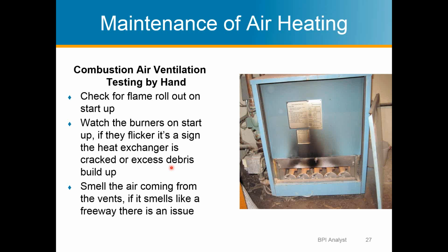When the large blower turns on to move air in the house, if you see disruption in your burner flame at that point, that's a sign of a cracked heat exchanger, and so you would want to investigate further. It may not be a cracked heat exchanger, it may be, but it's just one of the visible ways that you can see that there might be an issue.